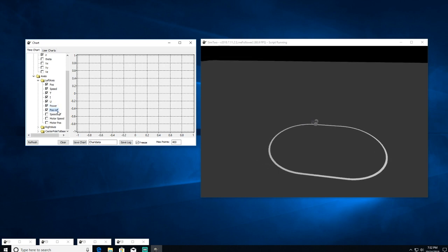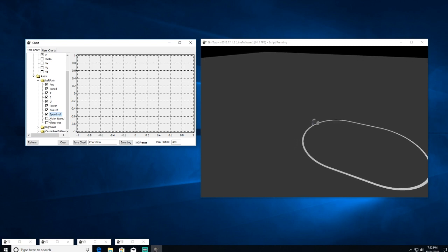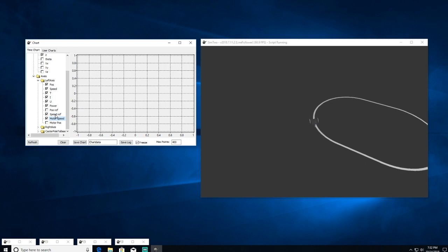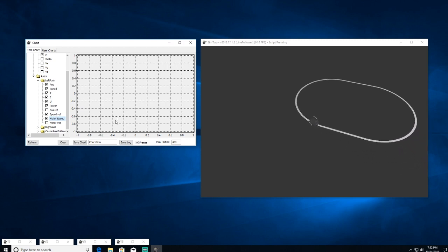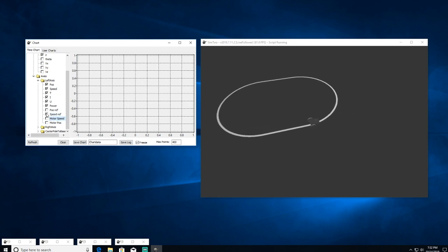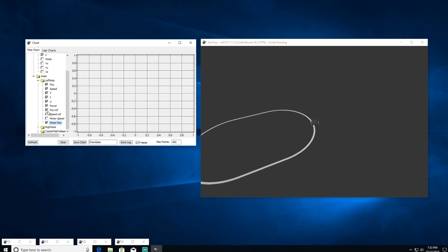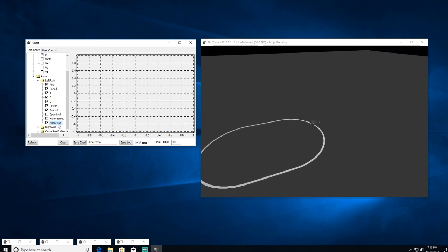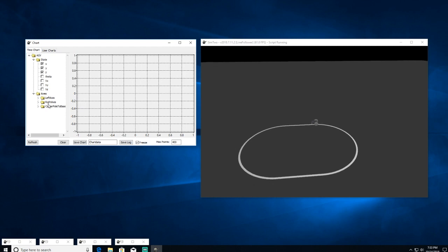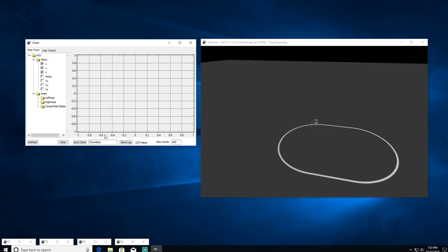You can see your position reference. And then, for example, you can calculate your following error based on your motor speed and your speed reference. So the difference is going to be your following error for the speed. And here, the position reference and motor position are going to give you the difference between your reference and your actual position. So you can do that for the left axis and right axis. So it's important to also use all the resources in your tab.